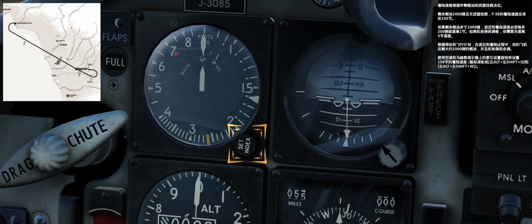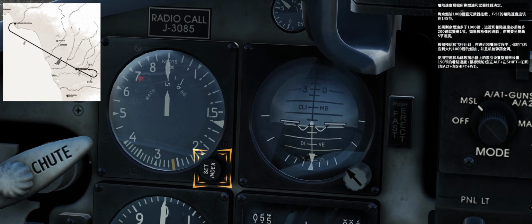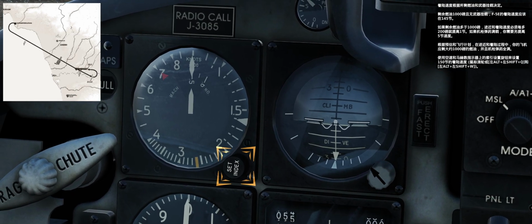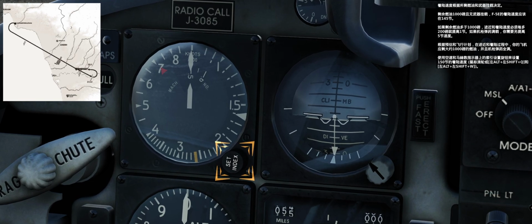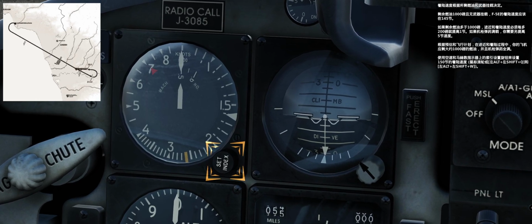Using the set index knob, set a calculated landing speed of 150 knots on the airspeed and Mach indicator with help of the mouse wheel or by pressing the left Alt plus left Shift plus Q and left Alt plus left Shift plus W keys.